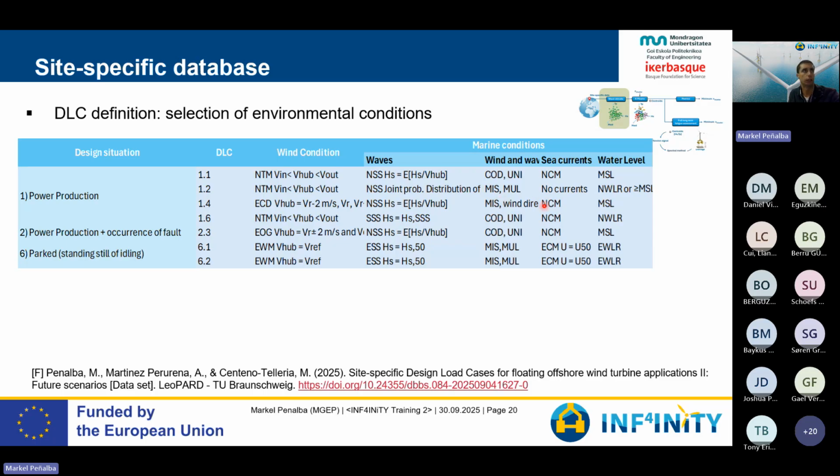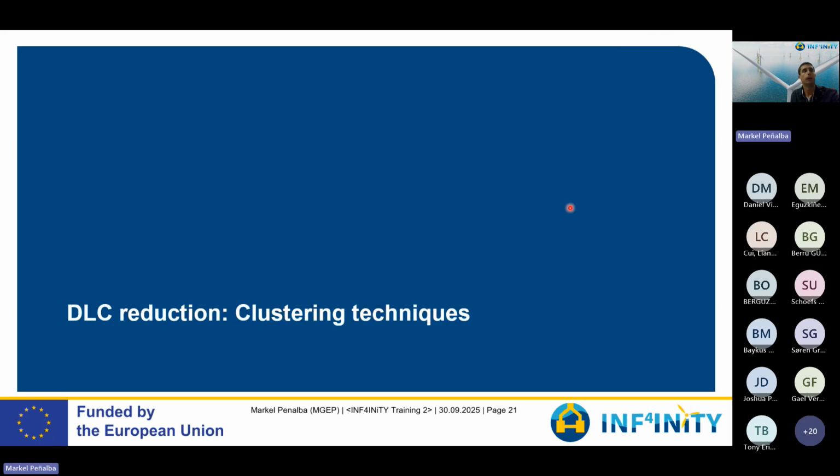So as you can see here in the fatigue analysis design load case, the 1.2, we do need to consider misalignments and also multidirectional cases, but sea currents are somehow neglected, as suggested earlier and also suggested in different standard guidelines and white papers. So I will focus on the design load case 1.2 and specifically now describe the clustering techniques we've been using or developing in this